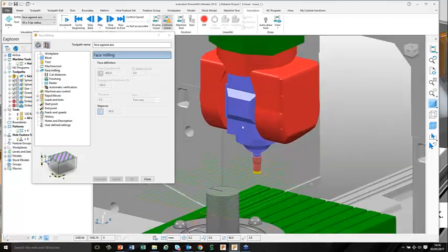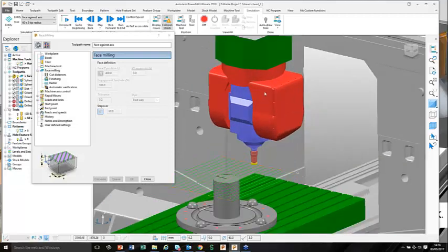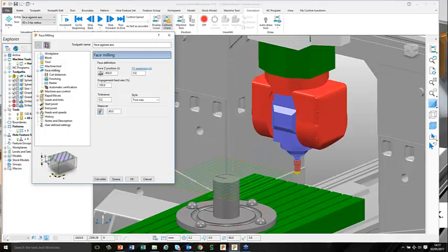Now, this is a relatively substantial machine tool, and some of these head-head machine tools are not as substantial as this. Some of the lighter weight machine tools have router type configurations. We could have quite a heavy cut on there, and we're pushing against the actual axis of the machine tool, so you're better off to push in this direction. For whatever reason, you may have a restriction and might only be able to machine in that direction. So we want to be able to position that head so we're pushing all the force of the machine tool at 90 degrees to where we are now.